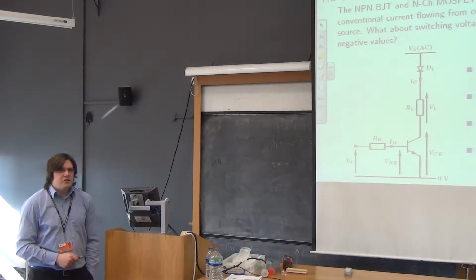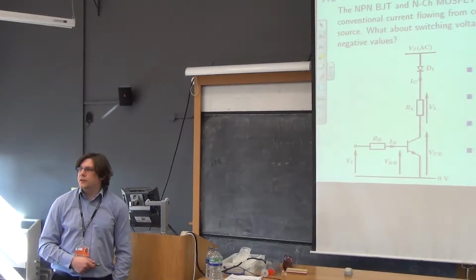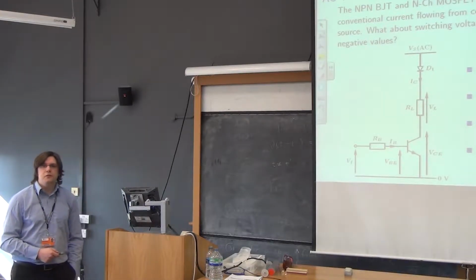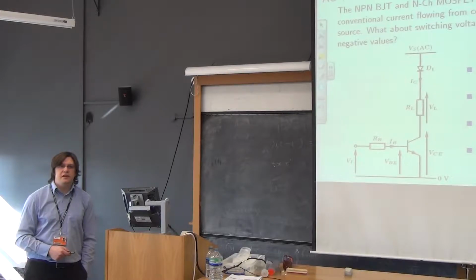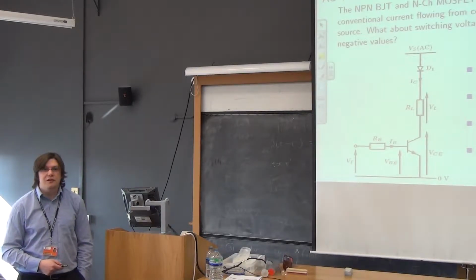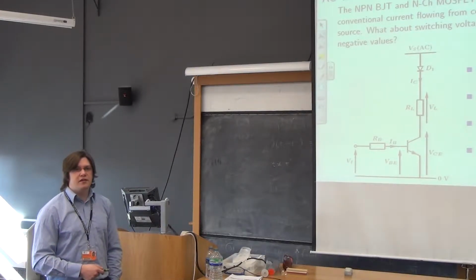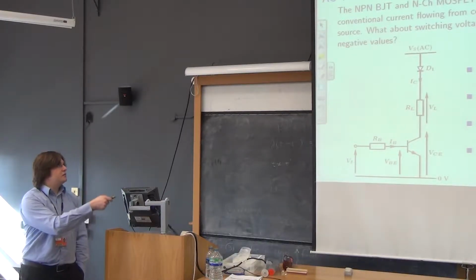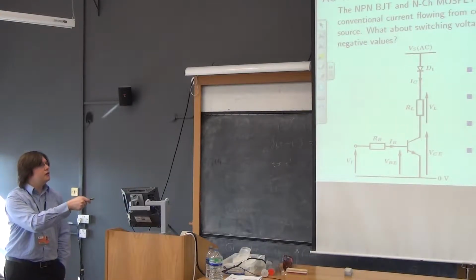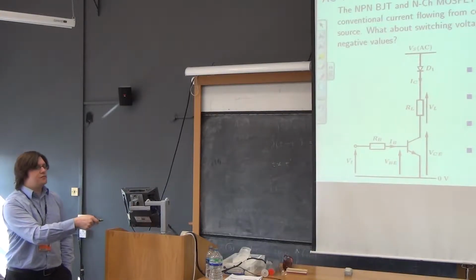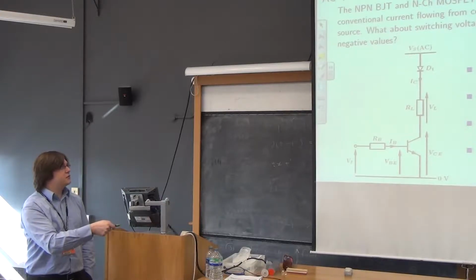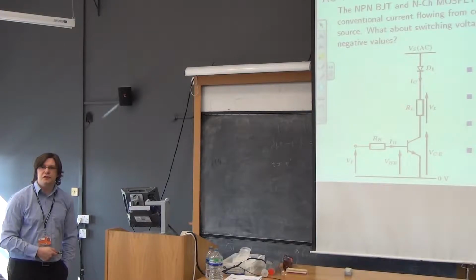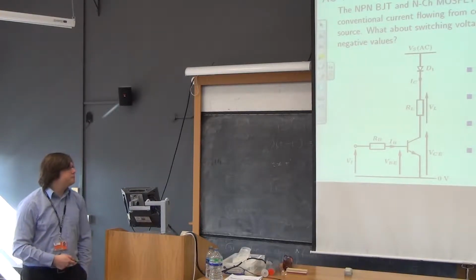And that means that essentially you're giving up half of your power dissipation in your load, which is certainly not ideal. It represents an efficiency loss of a half. So your best possible efficiency can now be a half, except it can't be because you've still got transistor dissipation and you've now got some extra dissipation in your diode, which is, if we say it's 0.7 volts across the diode, 0.7 times IC dissipated in it. So you'll be lucky to get 45% efficient if you really try.